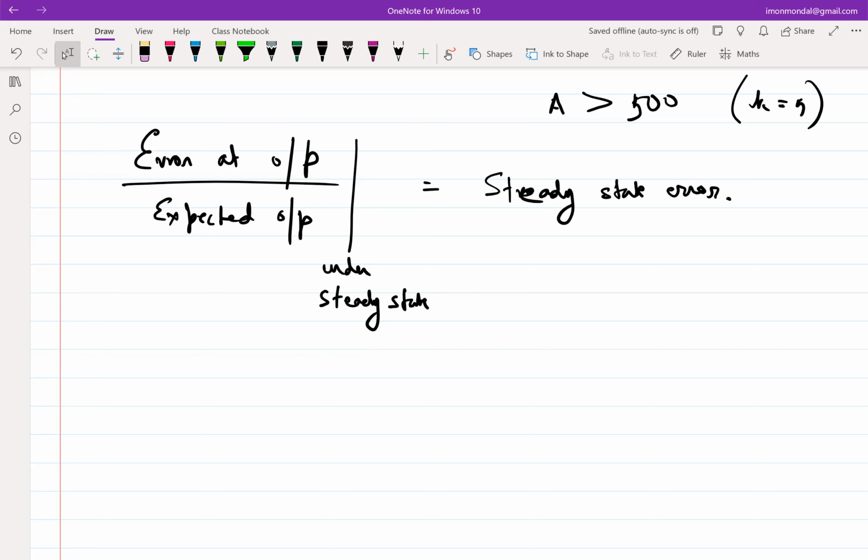An ADC is a way of sorting your voltages into multiple bins. In the sense that, let's say I have a voltage supply of 1 volt. And the ground is 0, and you have an input voltage of, let's say, 0.49 volts, right? So when I say I have a 10-bit ADC, what I'm essentially saying is I am dividing this 1 volt to 0 volt range into 2 power 10 equal size spacings, and I'm trying to figure out within which of these gaps this 0.49 volt resides, right?